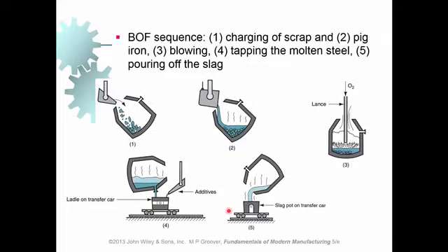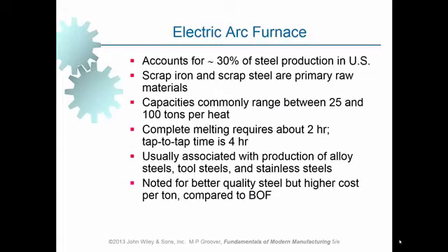So this is the one that is to be used for production of different types of steels and maybe cast irons. And if we want to add some alloying elements, this is the right place. Take a look at this. We are tapping pig iron, which is now processed with a lower amount of carbon. At the same time, because it is in the molten shape, we can add some additives, different types of alloying elements and whatever, in order to make different types of steels out of it.